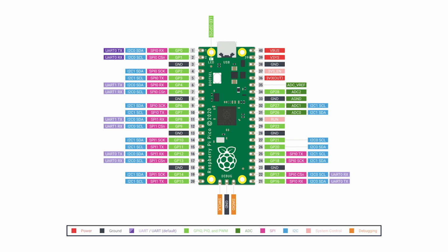The Raspberry Pi Pico offers a wide array of interfaces to allow you to connect to various devices. Our LCD panel uses an SPI interface, so you will need to use one of the 2 hardware SPI channels. We can use software to allow us to turn any GPIO pins into an SPI channel, but doing it that way runs much slower and uses up much more processing power than the hardware drivers.